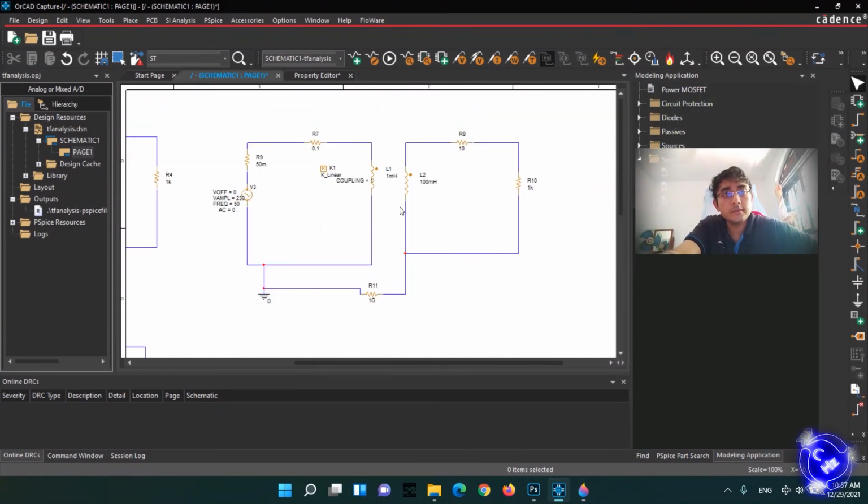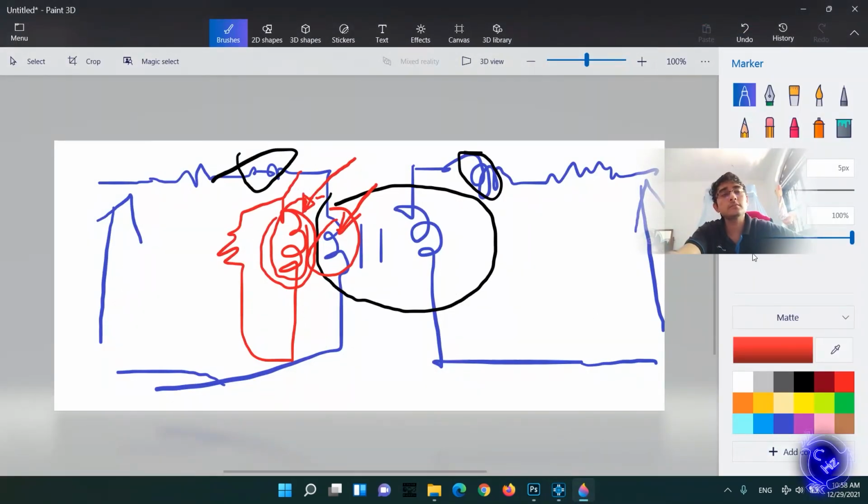This is the finite value. Right, let's see in PSPICE. Here, this is our magnetizing inductance, 1 millihenry. Here I didn't draw any ideal transformers. For an ideal transformer, the inductance value is infinity.